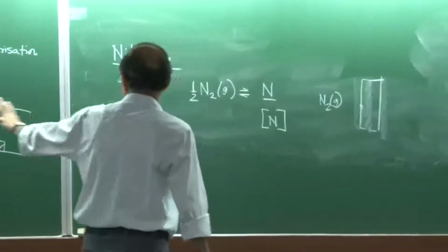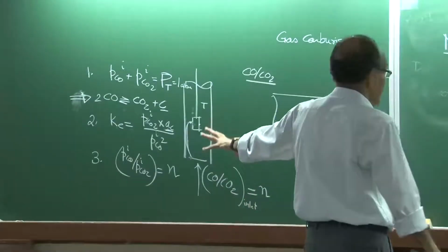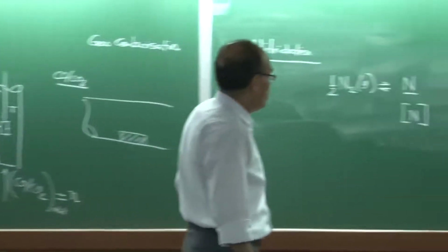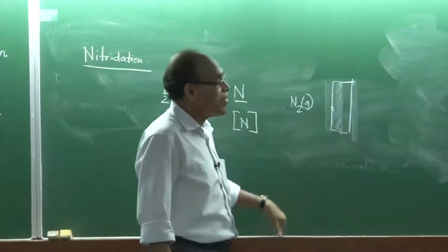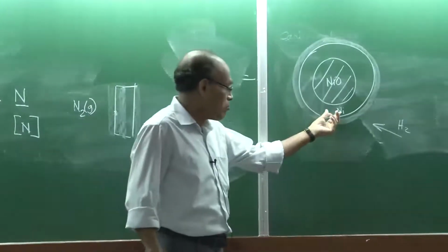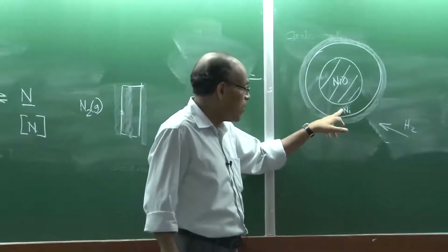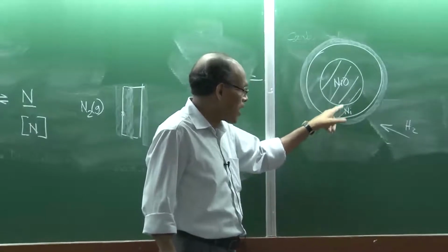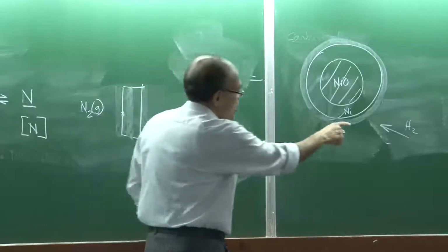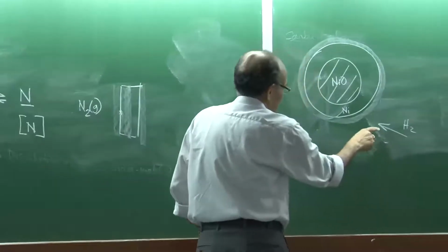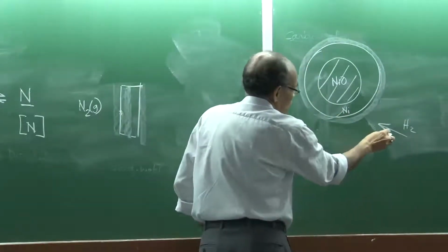In these problems, the carburization, because we are talking of solid state diffusions through dense medium, these are all dense medium. On the other hand, diffusion through solid nickel could be, when reduction takes place, a porous material. So if you consider this particular problem here, we see that we have a boundary.